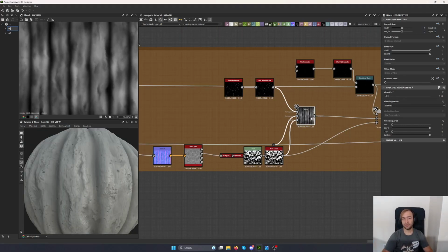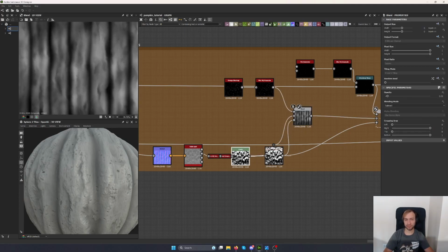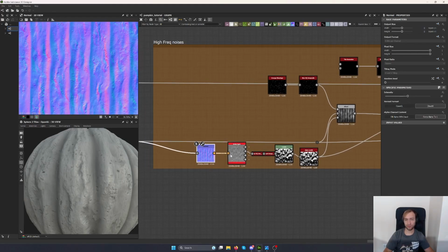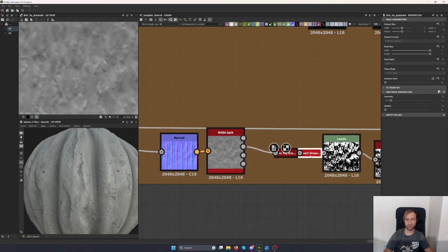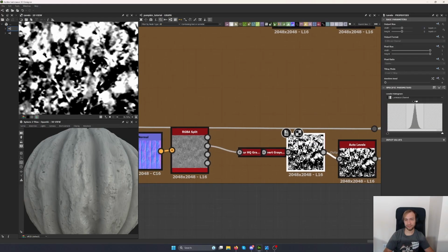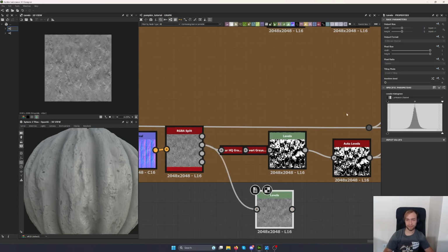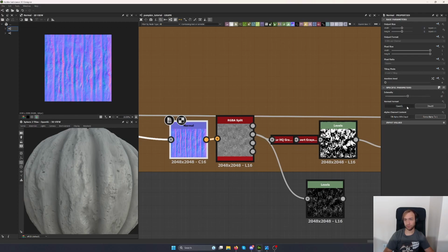And then I wanted to have some more dents or some more holes, but I wanted them to be only facing up, just adding a little bit of noise, but to the faces that are facing up. So we get a normal, we do an RGBA split, and here I'm just blurring, inverting, and auto levels to get all the shapes that are facing up. So basically we have that, but depends on if you're using OpenGL or DirectX.